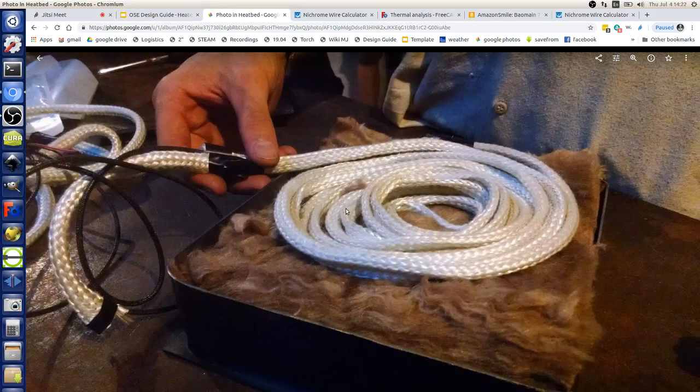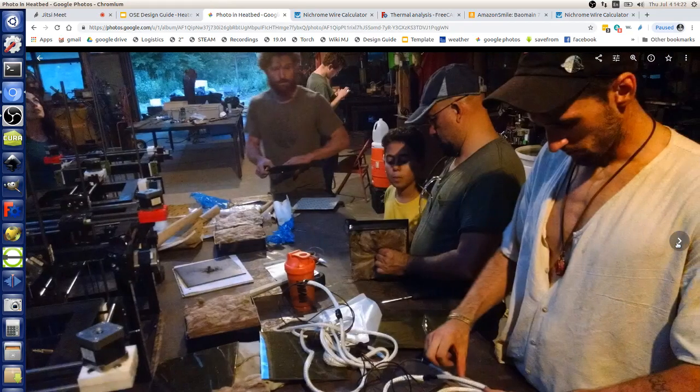We wrap the coil around, and then you connect it to high temperature wire. This is 200 Celsius copper wire, rated for applications where it can take a little bit of temperature, as opposed to plastic coating, which may be rated for, say, 80 Celsius.